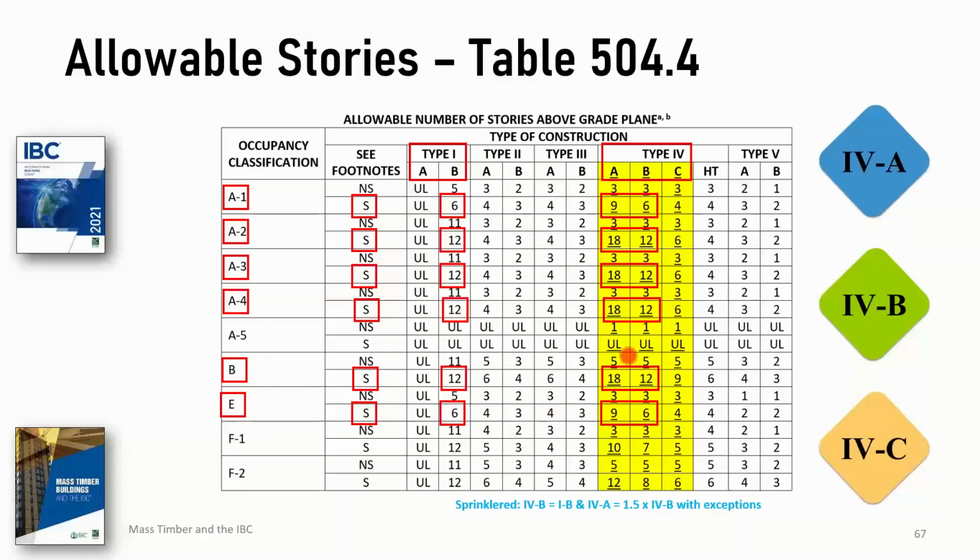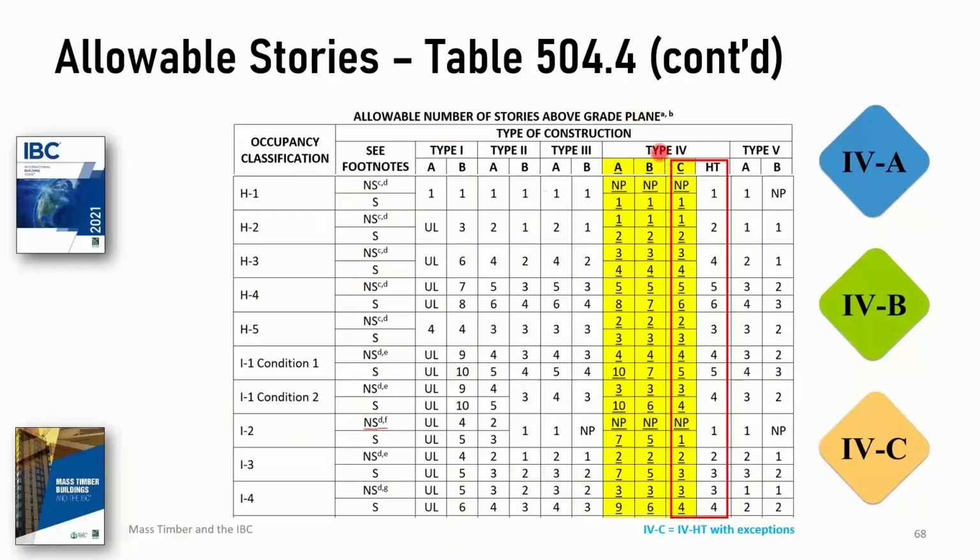Use group B, 18 stories. Those are the significant changes for this new, well, it's just everything's changed. It's a new construction type altogether. Let's look at the ones for the hazardous use groups, greatly reduced, as you can see. Institutional and I2 greatly reduced.